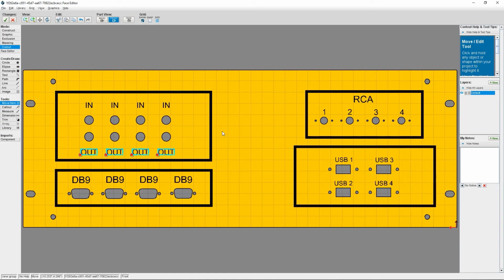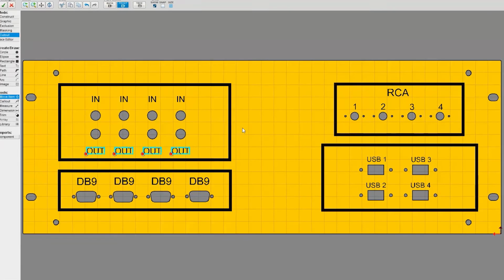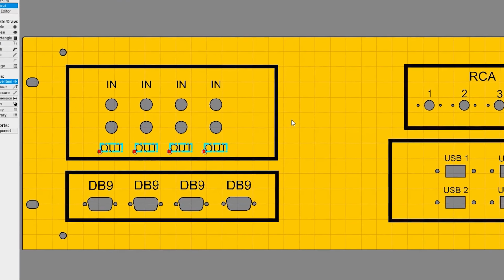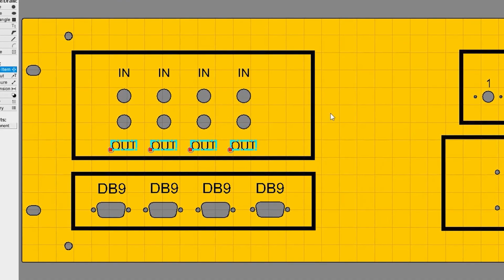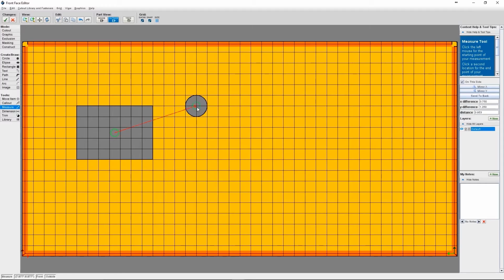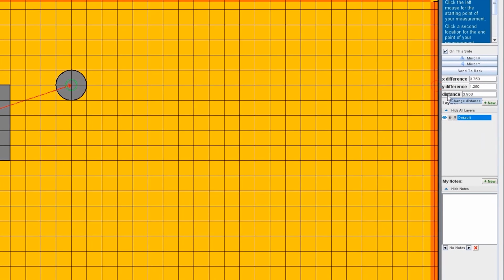One thing to remember that I didn't mention earlier, in order to distribute objects inside the software, you need to have 3 or more objects, because Protocase Designer needs to be able to detect the 2 objects on the outermost boundary. If you have less, you're better off using the measurement tool inside the software, and we have a link to that tutorial in the description below.